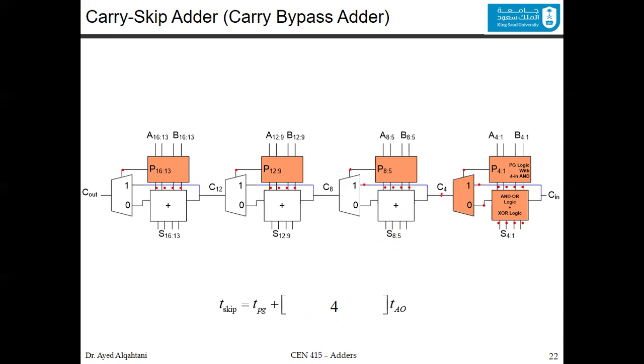You have the carry 4 and you have the signal already in the input of the mux at cycle number 4. At cycle number 5, this sum will start to show up its first bit, and you have the carry number 8 going to the first of the input. So the mux has done its job. At number 6, you are actually skipping. So you are doing this multiplexer.